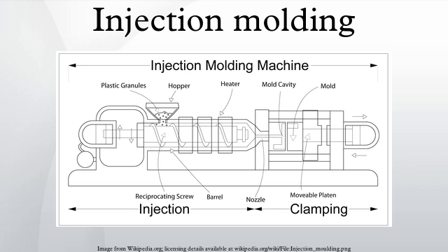Pre-hardened steel molds are less wear-resistant and are used for lower volume requirements or larger components. Their typical steel hardness is 38 to 45 on the Rockwell C scale. Hardened steel molds are heat-treated after machining. These are by far superior in terms of wear resistance and lifespan. Typical hardness ranges between 50 and 60 Rockwell C. Aluminum molds can cost substantially less, and when designed and machined with modern computerized equipment can be economical for molding tens or even hundreds of thousands of parts. Beryllium copper is used in areas of the mold that require fast heat removal or areas that see the most shear heat generated.